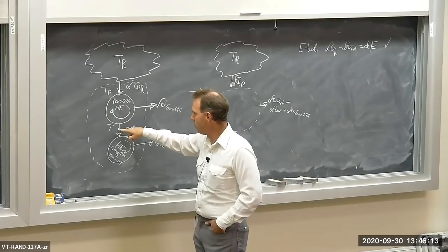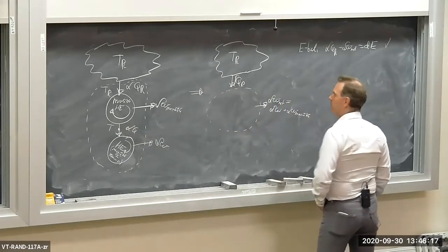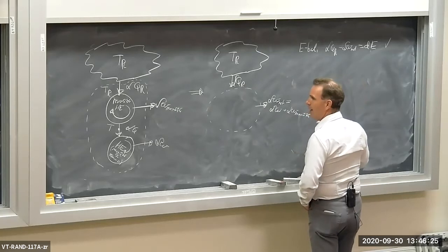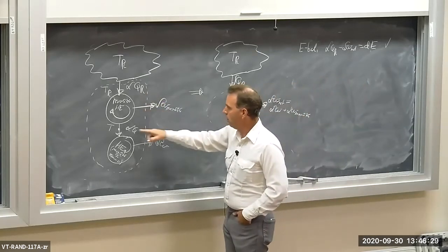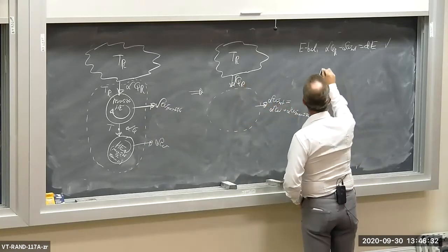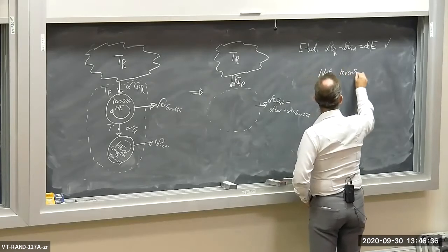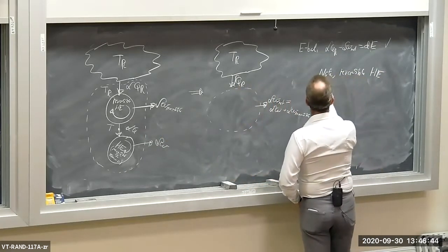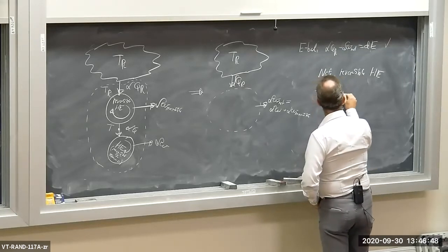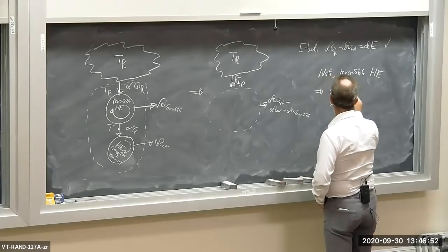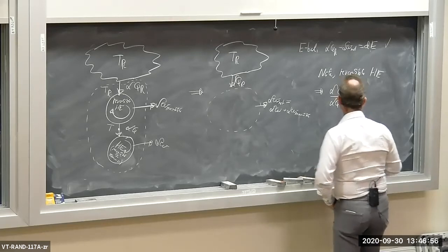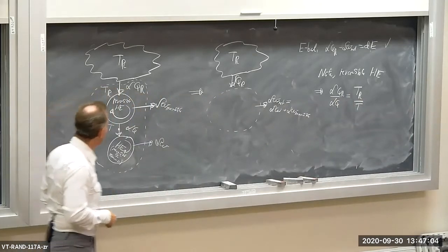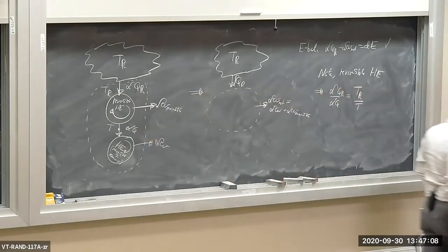We got the reservoir temperature and we have the temperature T. Because this guy is operating reversibly, we get that the ratio of the heat transfers, del QR over del Q, for the reversible heat engine, is equal to TR over T. Okay, reversible process going on here as far as the reversible heat engine is concerned, so that ratio of heat transfers, del QR over del Q, has got to equal TR over T.